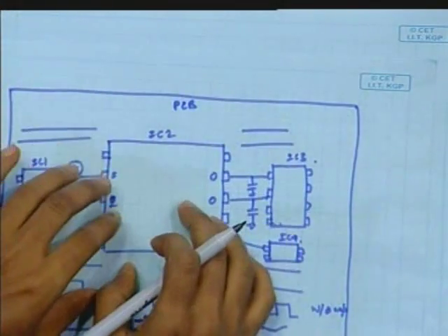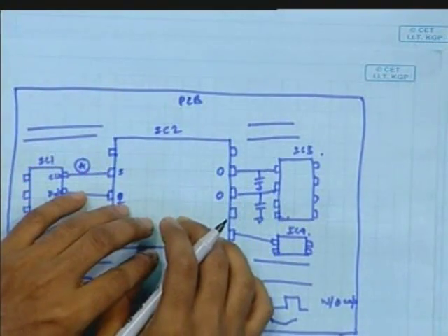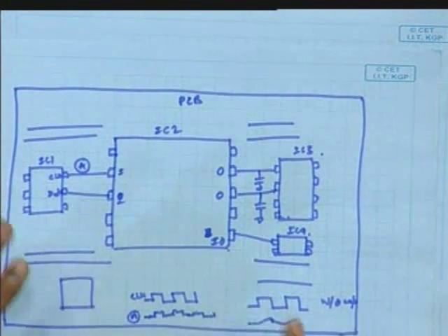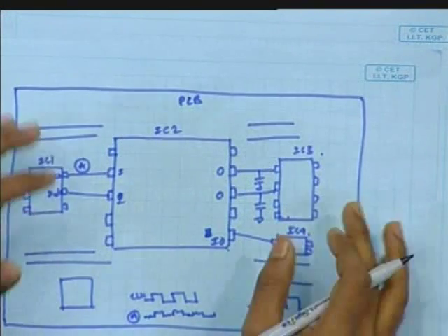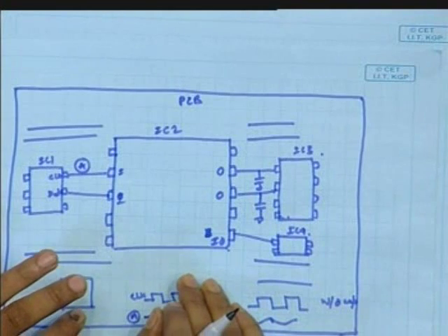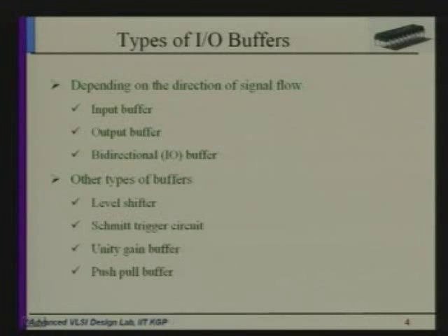Now if we see inside the IC, consider our design is IC2. We are planning to implement IC2, right? Now here we consider this is a 5 volt supply, so we are using 0.5 micrometer technology. Now if we want to get more speed, we have to reduce to a lower technology, right? So in recent processes you can find we can use two types of MOSFETs. One is 0.5 micrometer MOS, and we can use 0.35 micrometer also. So at that time we can use two, right?